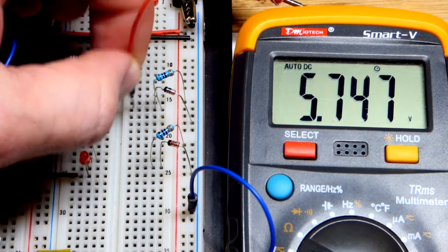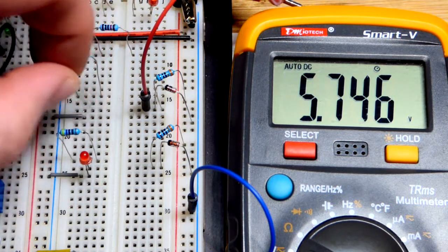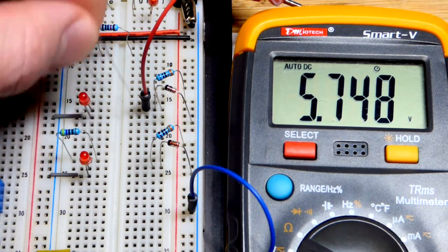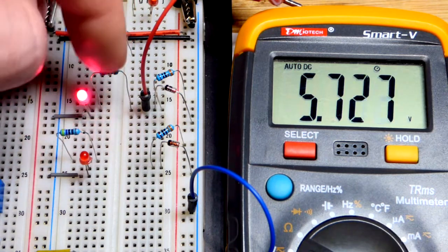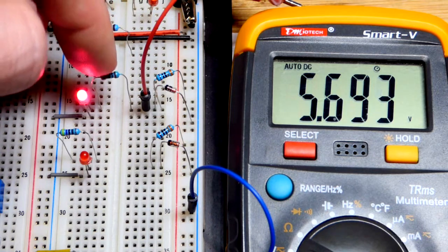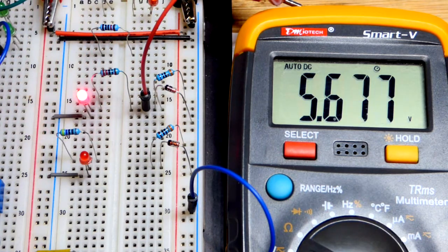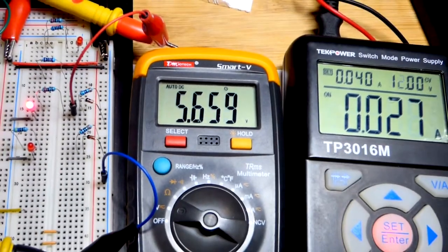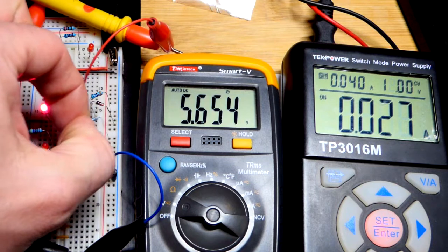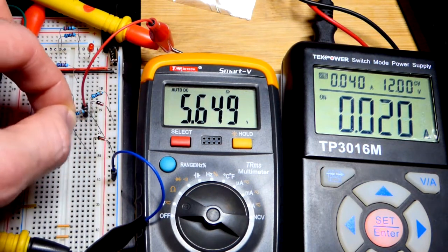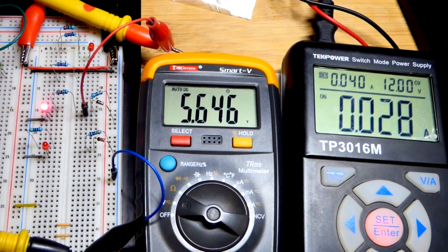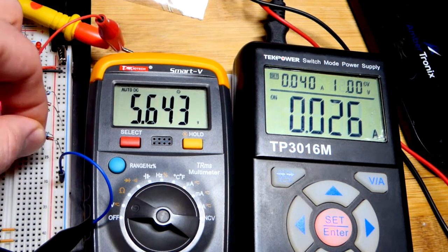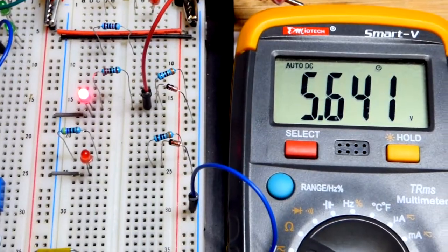So now, zooming in, I have an LED over here. This is our load. We already have it wired. The long lead, the anode, is up above the short lead, the cathode, because the short lead is going to that gray jumper. I'm going to grab this resistor, and you can see that this is a 220 ohm resistor. We only really want 5, maybe 6 volts across that resistor and LED. 6 volts is probably still okay. And we can get an idea of how much current is flowing, but realize that's also going through this other zener diode right there. So about 20 milliamps of current total through this circuitry up here. And so it's 28 now. I don't know if you could see that, so I'll do it again. 20 when we remove the resistor for the 9 volt zener diode. And so you can tell a lot by looking at the current on the supply.